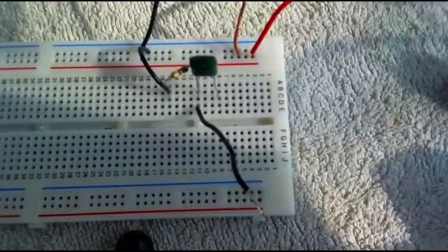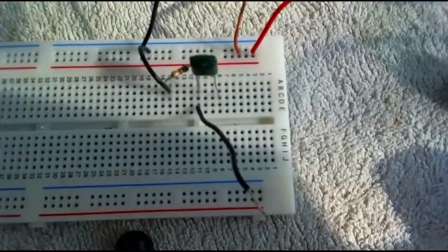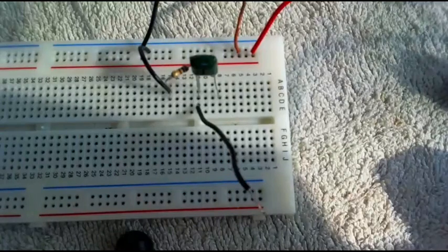Then I use F resonance related to the value for my known value for my capacitor, and I can back out the value of the portion of each of these inductive devices that I'm using as an inductor. So I'm going to end this recording and turn off the camera and then see you back with a Picoscope, and I'll have one or another inductor hooked up in series in a series resonant circuit, and we'll start making the measurements and identifying the inductance of these three different devices, two transformers and a switching device.